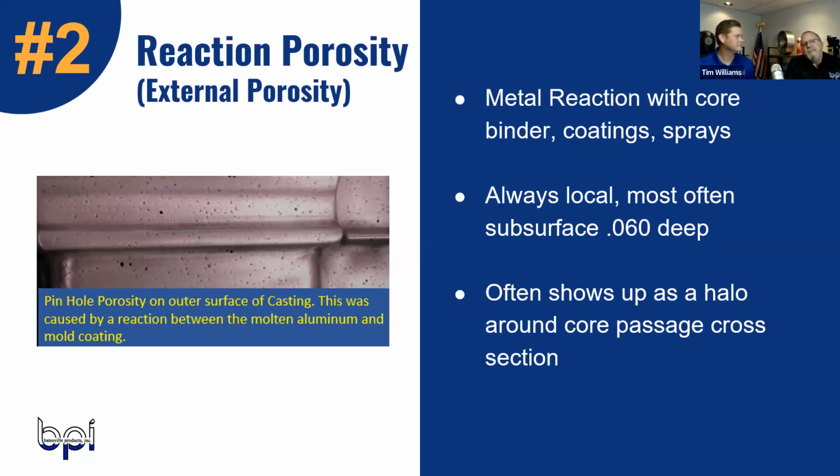I have a choice between water base and alcohol. We don't have an oven to cure the water base, so we are going into the alcohol and burn it off. And I think that's when Brad hopped in, and Brad called it what? Reaction porosity, absolutely. There you go. And the reason Monty said, you have to dry it.